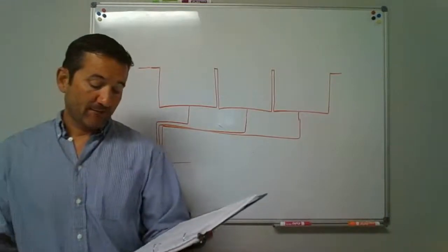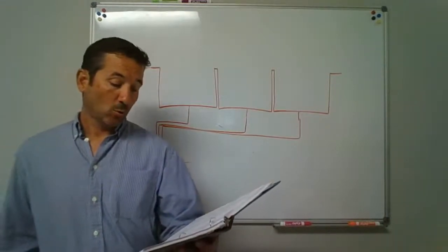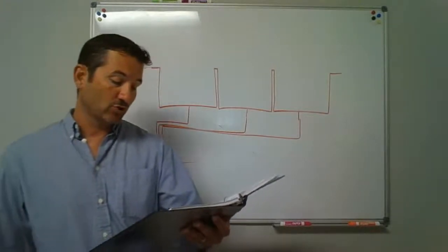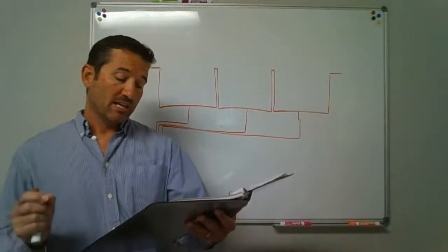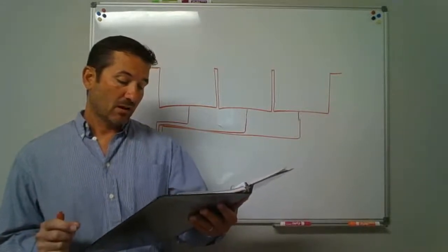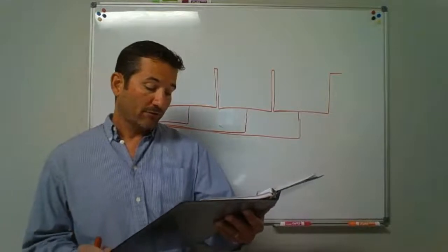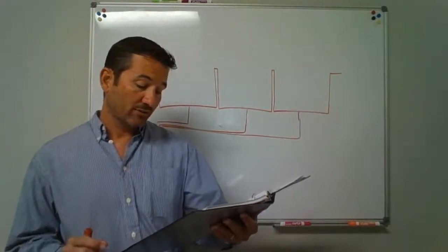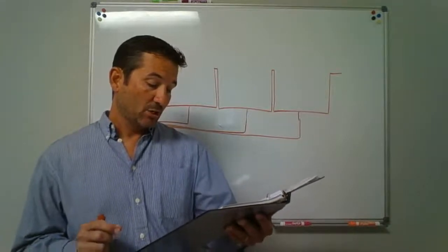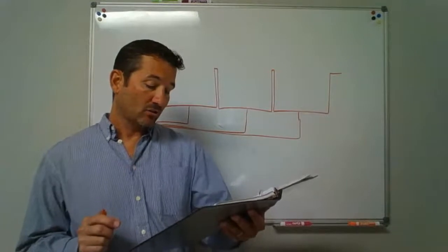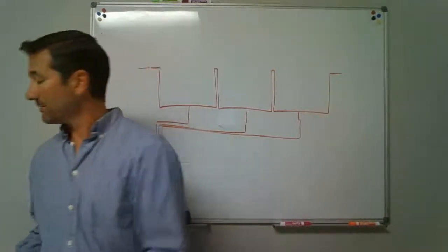Floor drains in food storage areas. Floor drains located within walk-in refrigerators or freezers in food service and food establishments shall be indirectly connected to the sanitary drainage system by means of an air gap. Where a floor drain is located within an area subject to freezing, the waste line serving the floor drain shall not be trapped and shall indirectly discharge into a waste receptor located outside of the area subject to freezing.